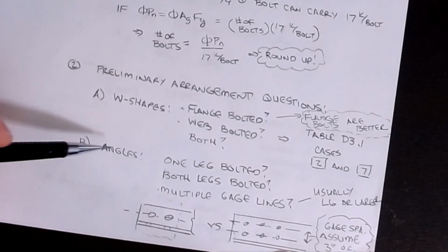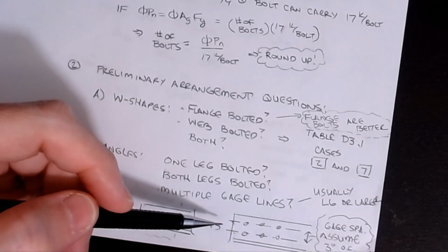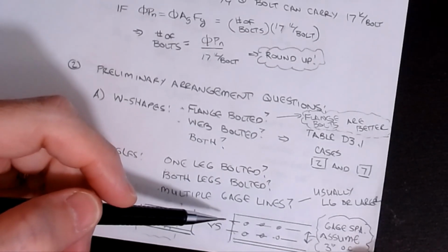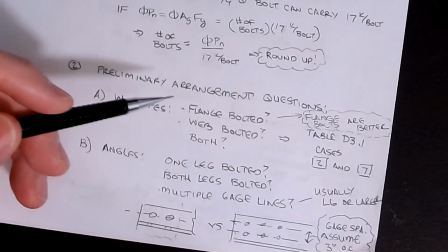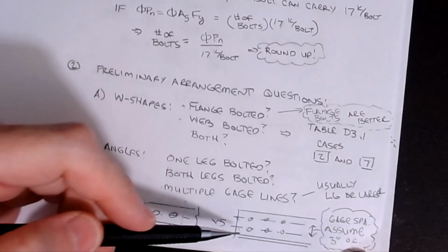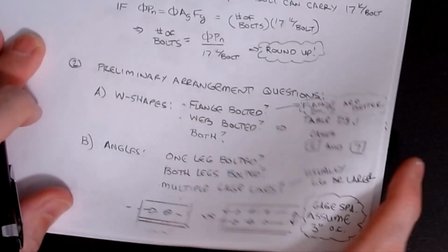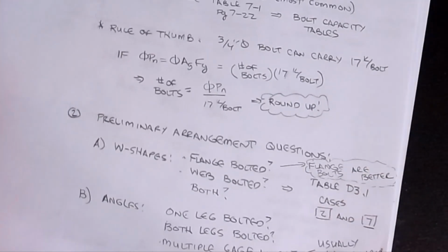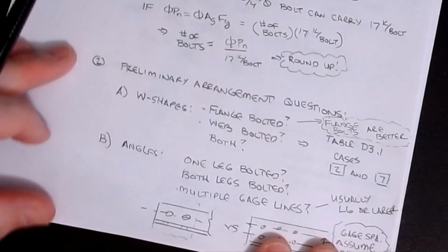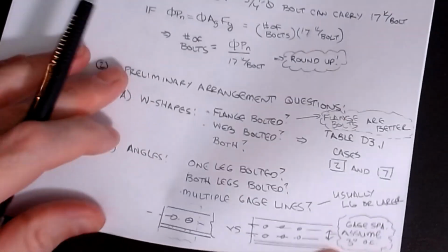Typically, we're looking at, like I say, an L6. It's kind of the classification here. Again, rule of thumb: use 3-inch spacings between these, in both directions. That's a fairly typical standard for construction for bolt pattern spacings.